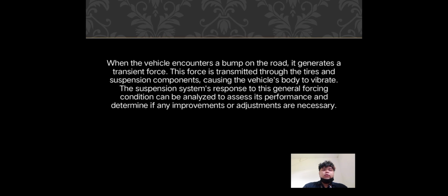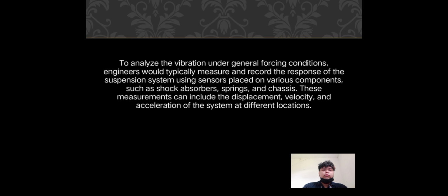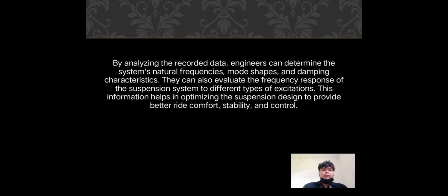To analyze vibration under general forcing conditions, engineers and researchers use techniques such as modal analysis, frequency response analysis, and time domain analysis. Modal analysis involves determining the natural frequency and mode shape of a system, which are essential in understanding its dynamic behavior. Frequency response analysis helps in understanding how the system responds to different frequencies of excitation, while time domain analysis examines the system's response over time.